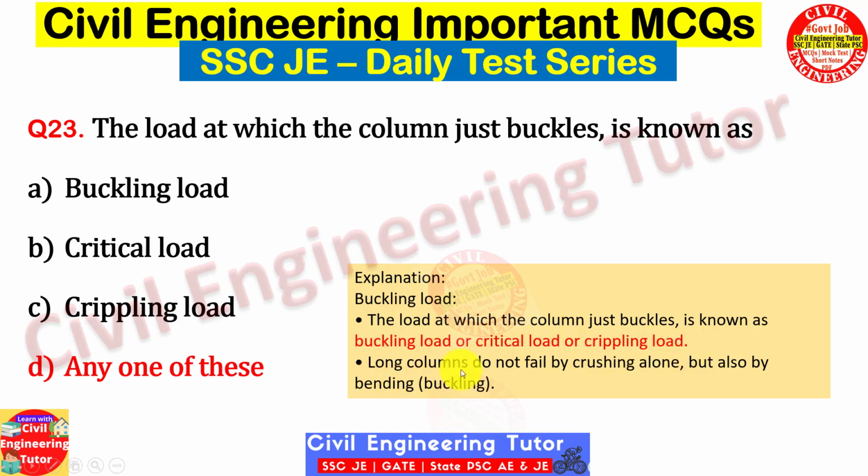Okay, so you have to remember this, that long columns do not fail generally by crushing alone. Long columns fail with crushing as well as bending, but the portion of bending is generally higher.